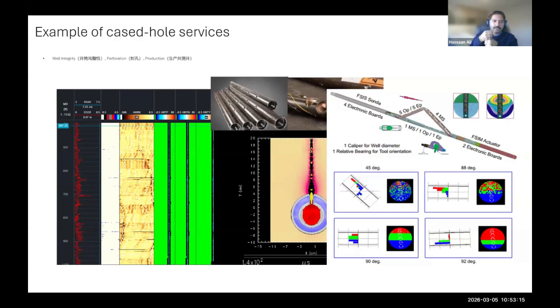The diameter of the coil tubing is very small, and it is made of materials which are very flexible. The flexibility, or malleability, of that tubing is such that you can actually roll it on a spool. Where it is used is primarily in heavy intervention operations, where you are using hydraulic tools, let's say, rather than explosives, to punch holes or do acid stimulation.